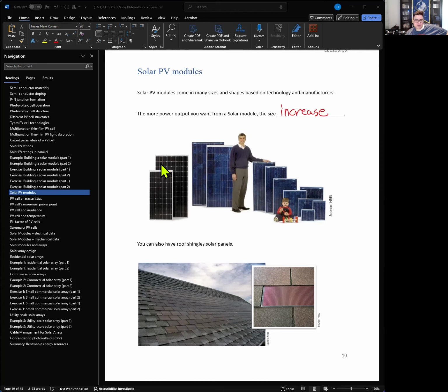Just to give you an idea of how tall everything is. These are your monocrystalline solar panels, or PV panels. This is your polycrystalline. You could tell because it's not as solid, right? And then different versions of it. So you can see small ones, big ones, all sorts in the middle. These you can actually count how many cells they have. If you look at it, you could go 1, 2, 3, 4, 5, 6. 1, 2, 3, 4, 5, 6, 7, 8, 9, 10, 11, 12. So this is 6 by 12, or a 72 cell panel. There's other ones a lot smaller, so this might be like a 51 or a 40 watt cell panel. So it really depends on how much power you want out of it, how much voltage.